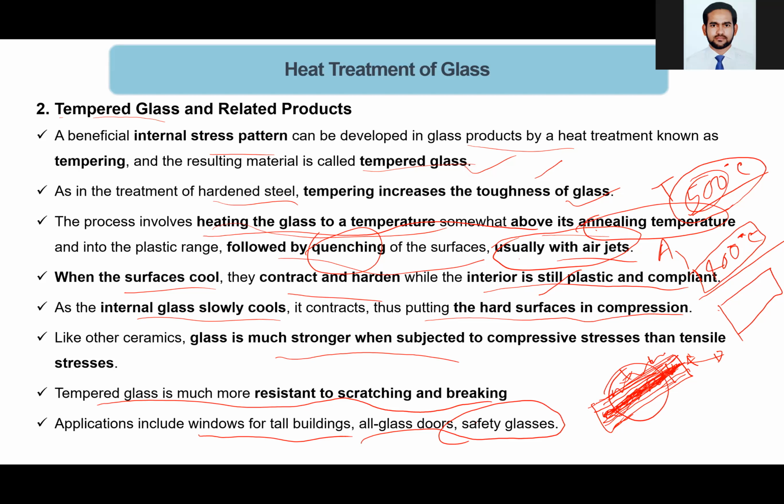All right. Okay, Abdullah. Sir, is there any difference between cooling and quenching? The term quenching is actually used for cooling, but this term is especially used for heat treatment purposes, because quenching does not mean simple cooling. It means you can cool it at various temperatures. That's why it's a different term. It is cooling, but especially used in heat treatment.